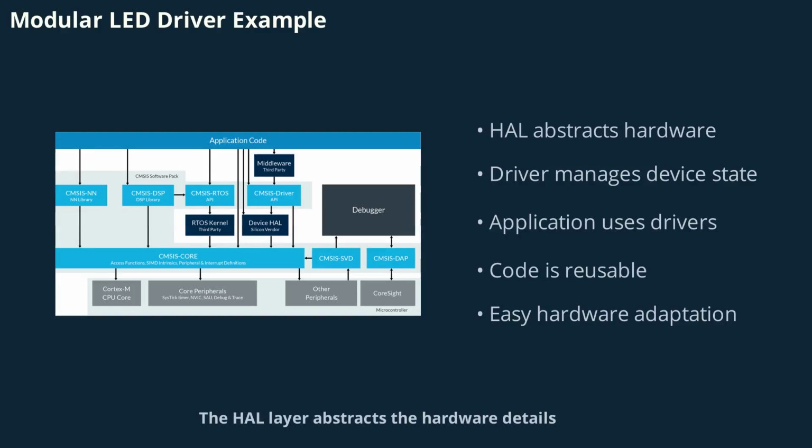The HAL layer abstracts the hardware details, while the driver layer manages device control and state. The application layer uses these drivers to implement system logic, such as blinking a status LED. This separation allows you to reuse code across projects and adapt to different hardware with minimal changes.